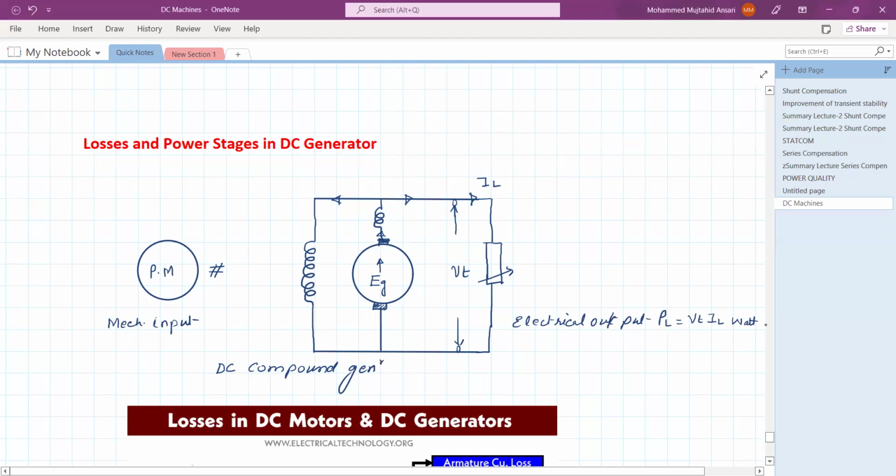So this generator has a shunt field winding RSH. The current flowing in the shunt field winding is ISH. The generator induced EMF is EG, and it delivers the armature current IA. The series field resistance is RSE. The shunt field resistance is higher because it is connected in parallel with the armature EMF, whereas the series field resistance and armature resistance are small. It may be 0.1 or less than 0.1 ohm.